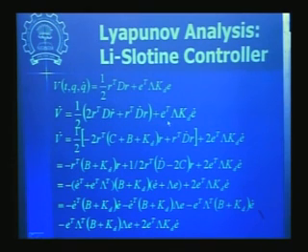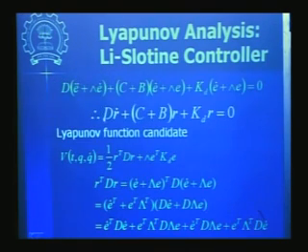And here it will become 2 times, I'm sorry, the 2 is missing in this part. This will become 2 times E dot transpose lambda Kd E dot, or E transpose lambda Kd E dot, or E dot transpose lambda Kd E. Both are the same terms because of the symmetry property. Now this D times r dot, you recall from the previous case, our basic equation.